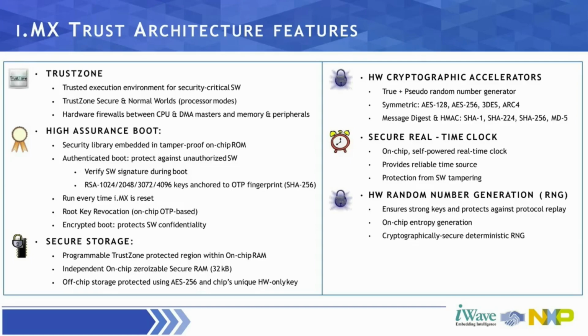For software protection, IP protection and confidentiality, we do support encrypted boot. It's AES 256, and the way the encrypted boot is done is basically tied to the chip, meaning that we can protect against cloning. Secure storage is basically tied to our tamper detection event.